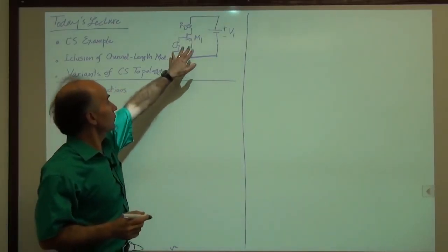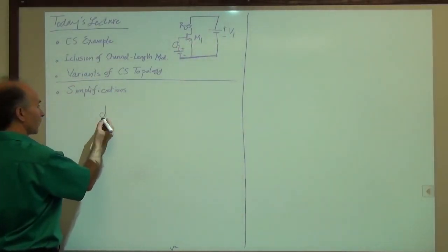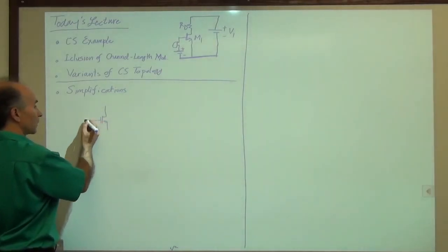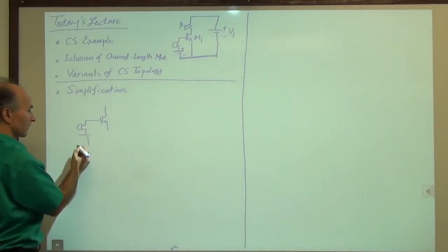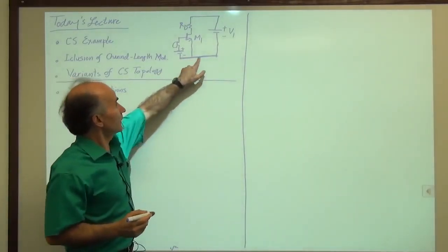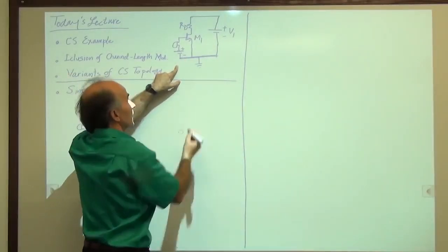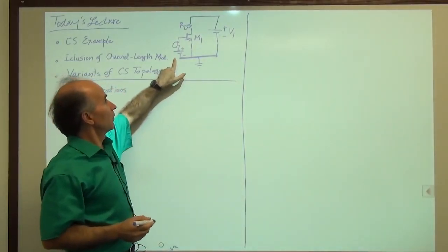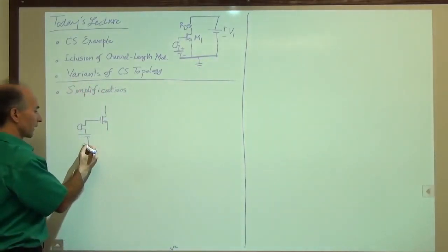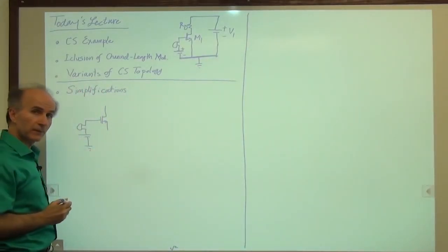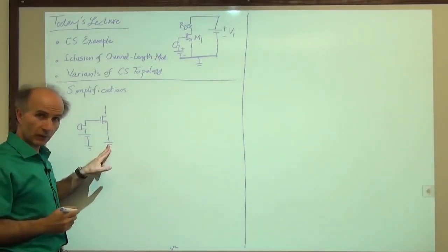Okay, so oftentimes we draw the circuit as shown down here. We have our MOSFET along with the input. So the input consists of a microphone and a bias voltage. And we call this common line here the ground. And sometimes we don't even want to draw one continuous line for all of these. So we just draw a ground symbol here. Similarly for the source, because it's connected to ground, we draw a ground symbol here.